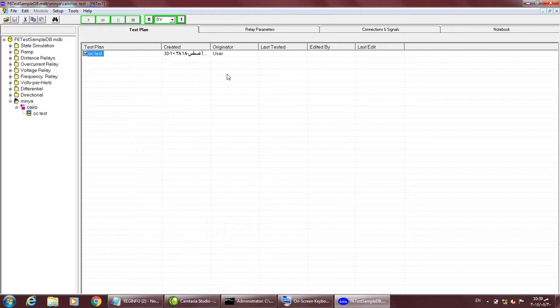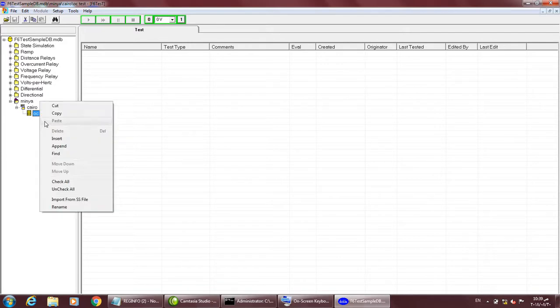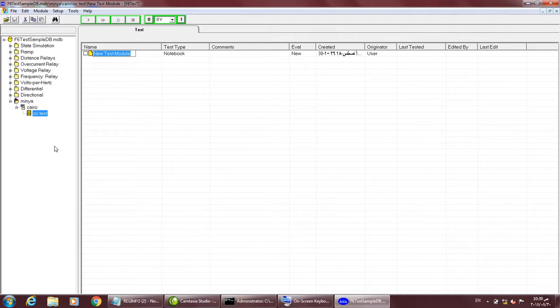Again, when you go inside, you have finally the test type. So first is location, second is relay, third is which protection, and in that protection what tests are there. This is the sequence you have to follow. This needs to be done only once, and it can be used as many times as you want. So here I am again doing append for the test types now. Yes, append. So suppose we want to test the pickup current of the relay.